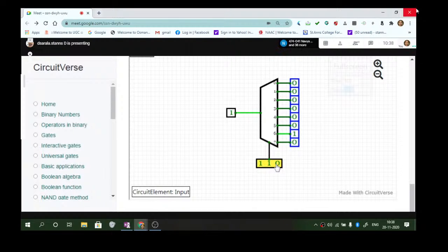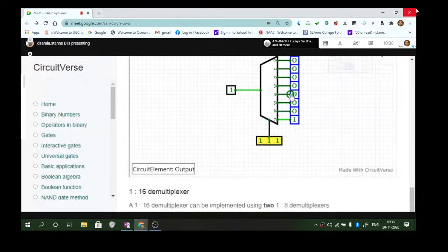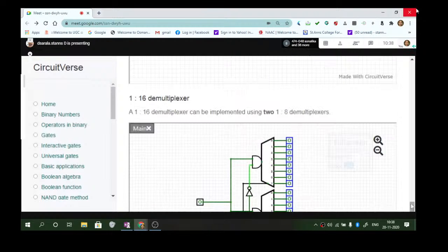How do you read this as 1 0 1? 1 0 1 is 5. Can you see 5? Similarly, 1 1 0. 1 1 0 is 6, it is changing here. All ones is 7, it is changing here. So this is how it will be working, and this is using an integrated multiplexer chip that is shown here. You have to construct them using, what should you use? You must use your AND gates, inverter and OR gate, and however I have shown you, it should be constructed like that. Let me show you.